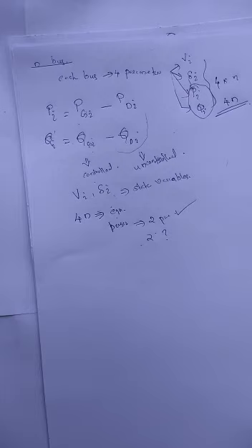If the voltage is very low, we classify it as a weak bus, and we can employ compensators like capacitor banks to enhance the voltage there. So power flow analysis is used for such activities and for future planning and extensions. I told you all this to make you understand that in a power flow analysis we get our solution firstly for V and delta. I hope you understood why we solve for V and delta.